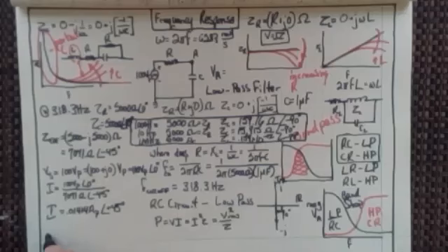So let's just look at the voltage drop. I'm going to write it as a voltage drop. What is the voltage drop across that first resistor? We know what the current is now. We know what the resistance of the resistor is. So we can come up with the voltage drop, because it's just, in this case, IR, isn't it?